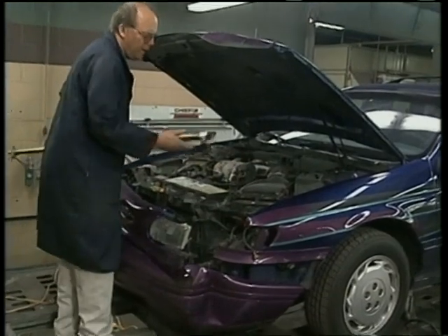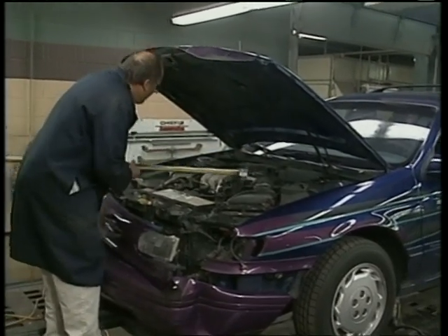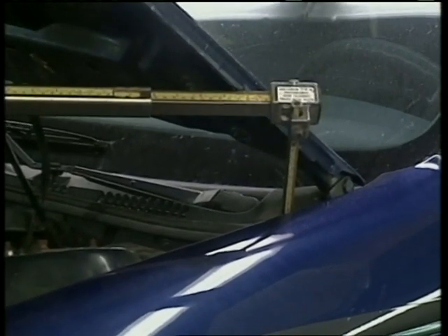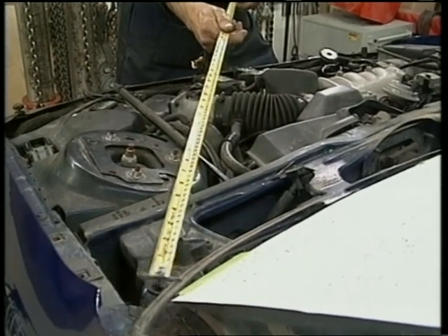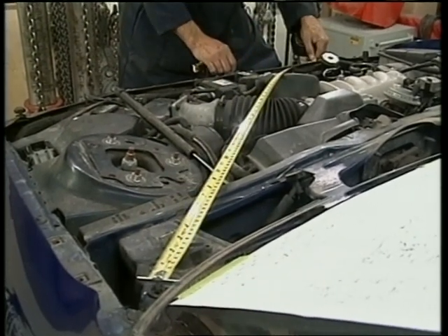A tape measure or tram bar can be used to make most measurements. A tram bar is a measuring rod with two adjustable pointers attached to it. The pointers adjust for height and length. A tape measure or tram bar measures one dimension at a time and must be cross-checked using additional reference points.